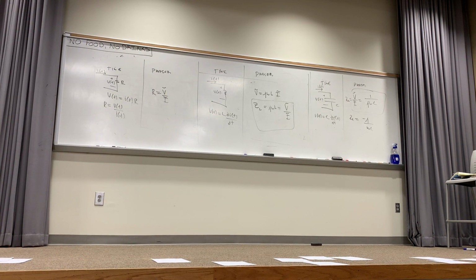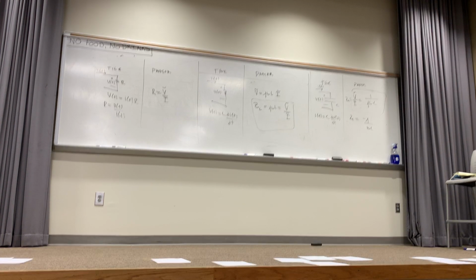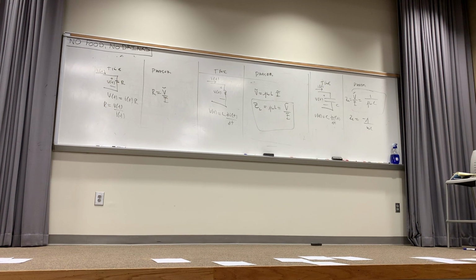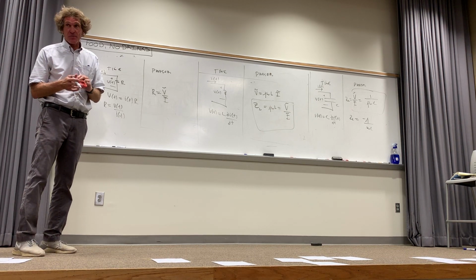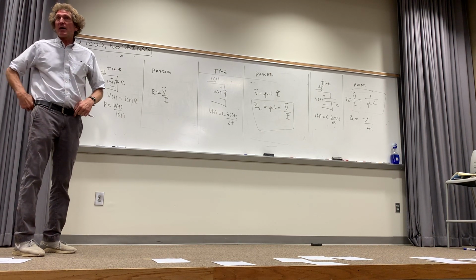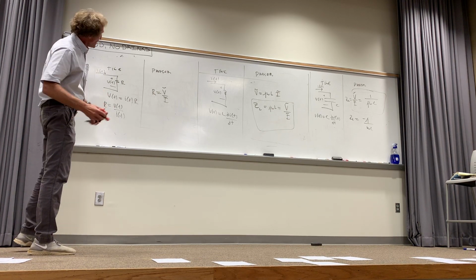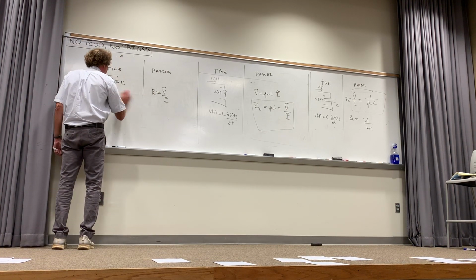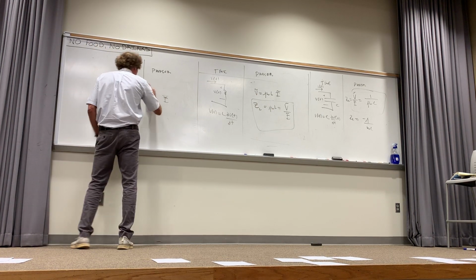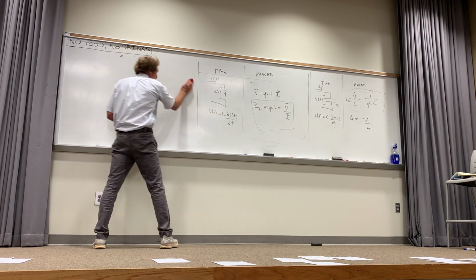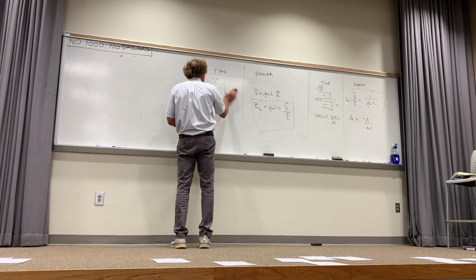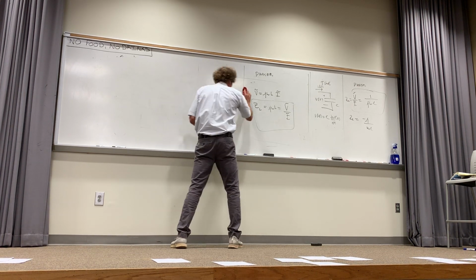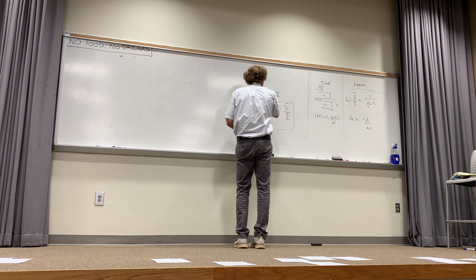Now, I'm going to tell you this. Most of the time, when you're beginning AC problems, they will specify the impedance of the capacitor or inductor as either like j50 ohms or minus j50 ohms, something like that. And you don't have to do the omega times L or omega times C most of the time, not all the time. Follow me? I want to do some simple problems to help you see this. And then I'll show you all the way how to get back to the time domain with the final answer. Because you're going to apply what you've learned earlier with all the different circuit analysis tricks to now circuits with capacitors and inductors.